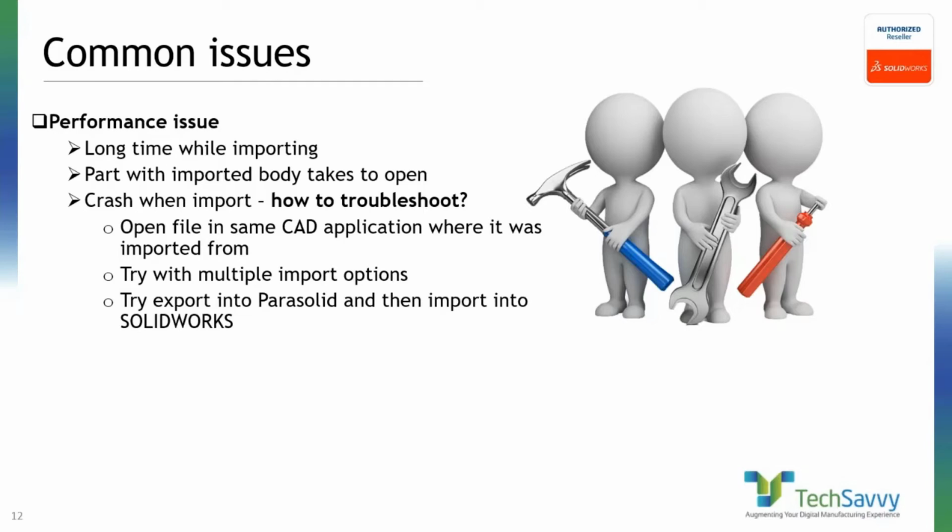A question might be coming to your mind: why have I mentioned Parasolid? As many of you might know, Parasolid is the kernel on which SolidWorks is based. So it is easier for SolidWorks to read and interpret the data which we convert into Parasolid. The best practice is to try to import the file as Parasolid.